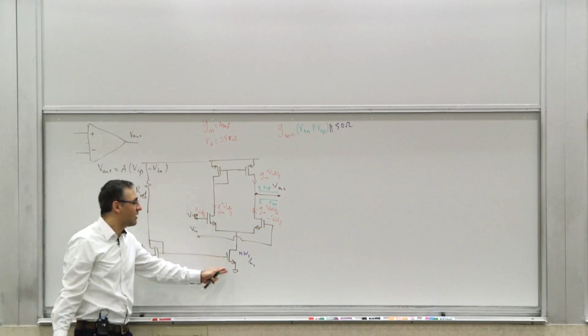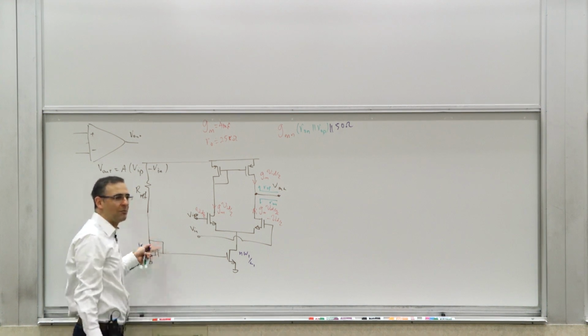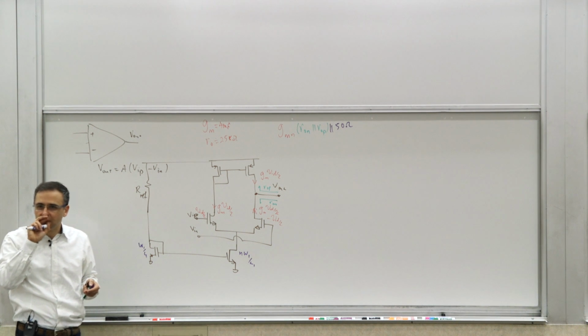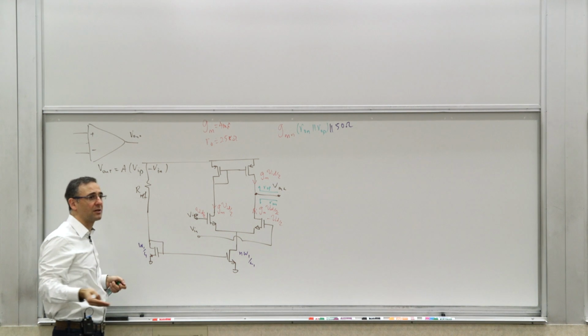So if you're establishing, let's say, 100 microamps here, I want this to be like 2 microamps, 1 microamp, 5 microamps, right? Because otherwise I would be burning twice as much power, and half of it is burned in this reference branch.